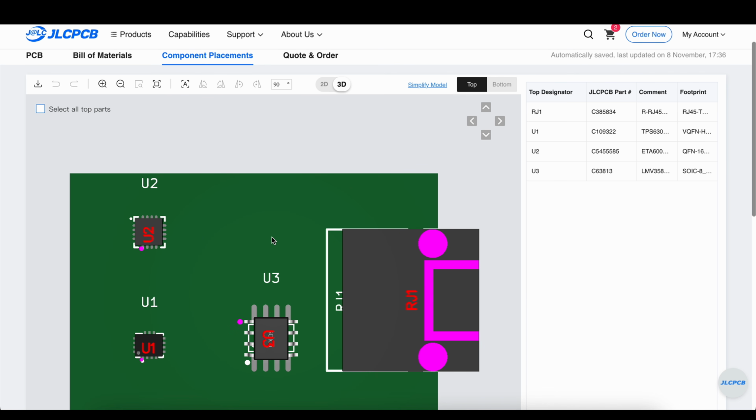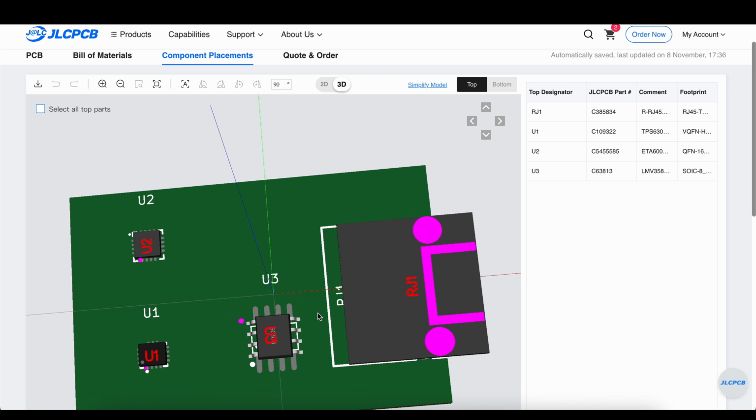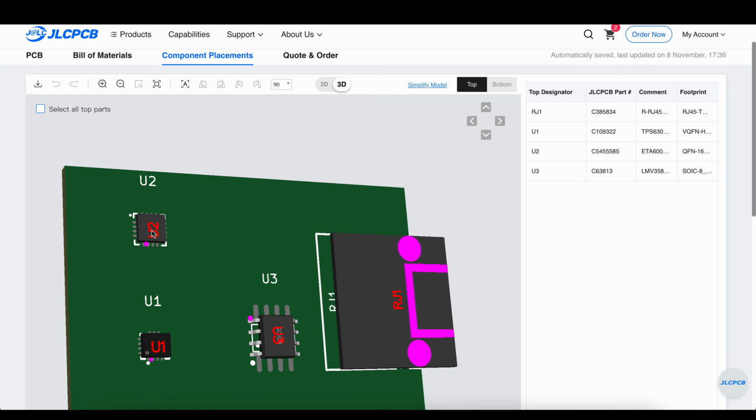So already we can see some things are wrong here. This is an op amp and you can see clearly it's rotated 90 or 270 degrees off of what it should be. That's fatal. It's just not going to work. This component is the lone component that's placed properly, and then you can see this component here is also rotated 90 degrees. This is fatal.